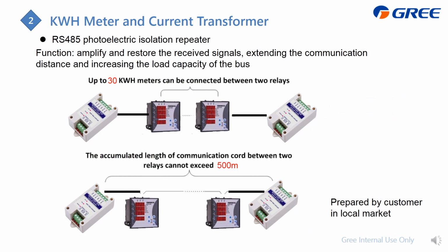This is the RS485 repeater, and in your project, if you find that for the power meter, there are more than 30 of them, or the total wiring length of this RS485 is too long to ensure the communication, we require to use this RS485 repeater. But for this one, you need to prepare it yourself on your local market.